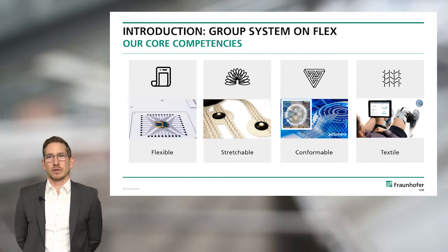In the field of stretchable electronics, we are working mostly on different substrate technologies, for example substituting polyimide with polyurethane and other derivatives, focusing on the substrate materials and on the assembly of these substrate materials. Conformable electronics is, in our view, something where we also work with thermoplastic substrates.